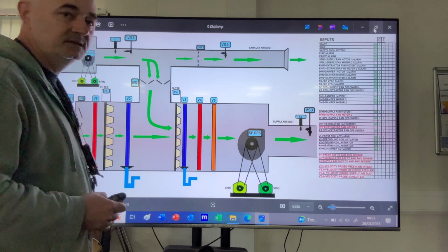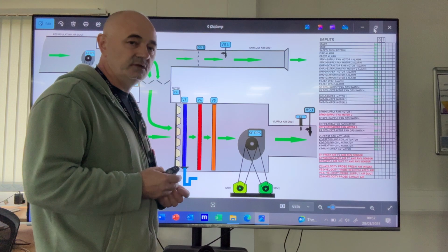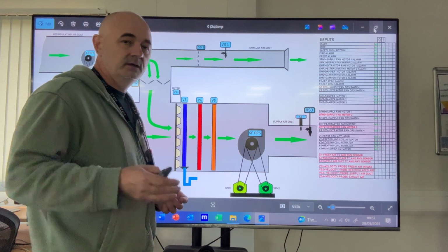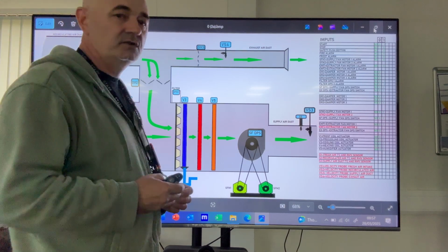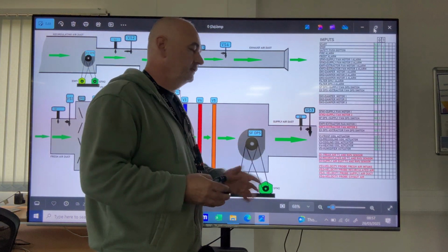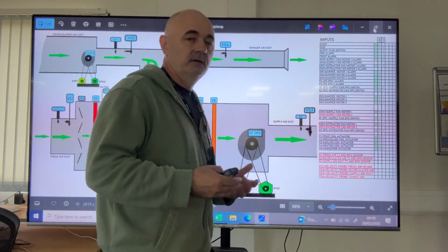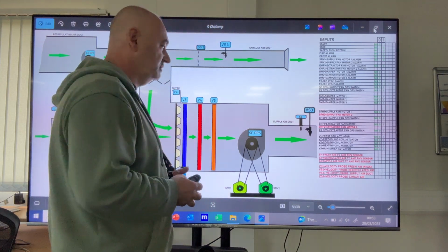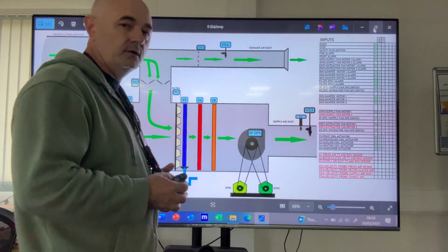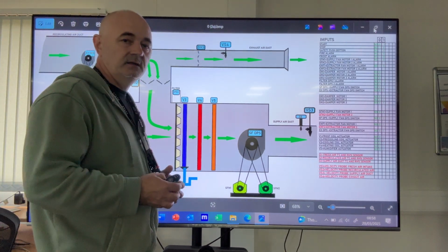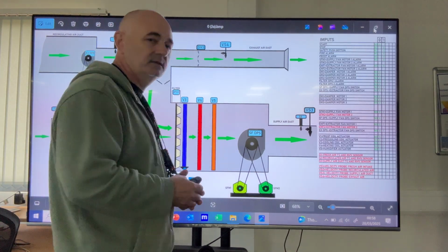Another important thing is that the air handling unit control philosophy should be written by an HVAC specialist, and the control philosophy will be communicated to a software engineer, who will apply the control philosophy in the software. Then the HVAC specialist will test the AHU's function to see if there's any glitch in the control philosophy or in the software algorithm which runs the unit.